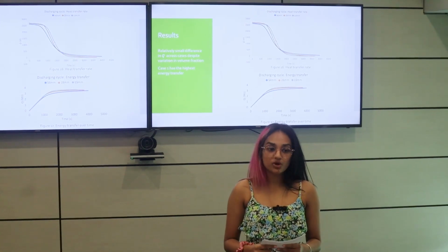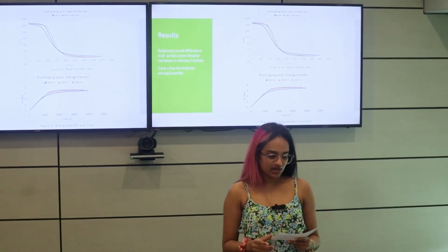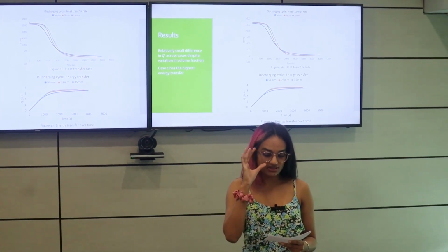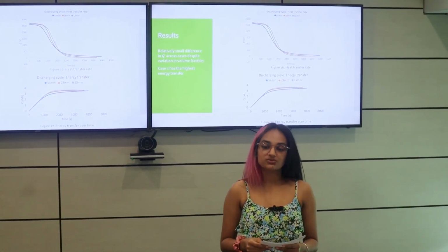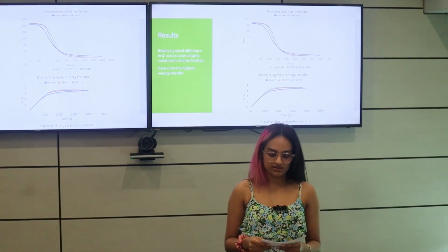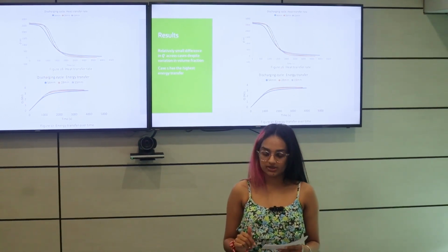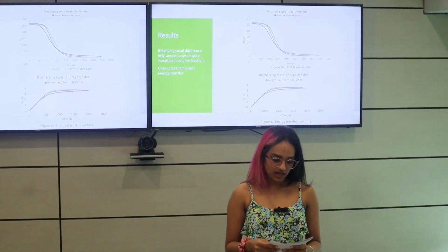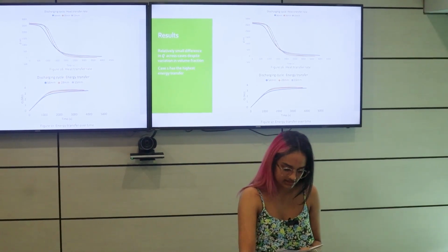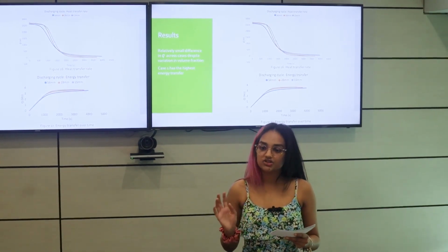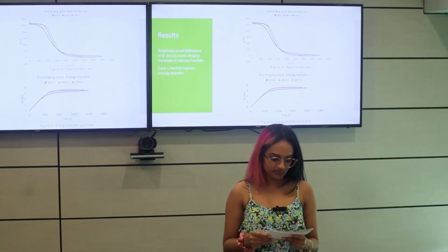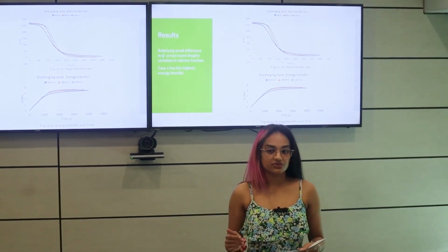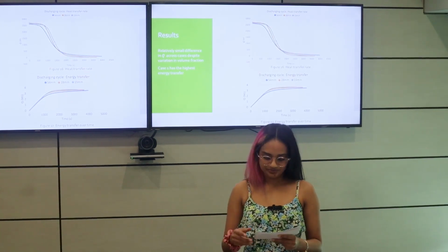The next results are the most important from this experiment. Figure 16 represents the heat transfer rate across all 3 cases during the discharging cycle. The heat transfer rate represents the amount of energy that is transferred from the wax to the water. This is an indicator of the effectiveness of each case. It can be seen in figures 16 and 17 that there is not a large difference between the 3 cases, despite the large difference in the amount of wax per case.